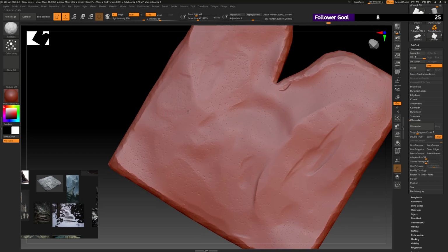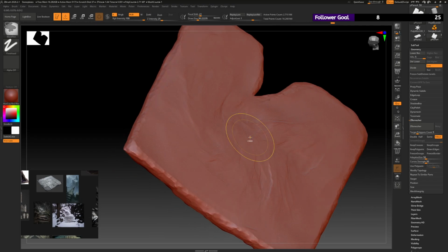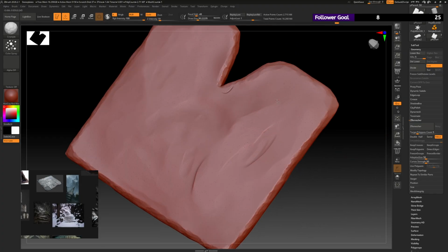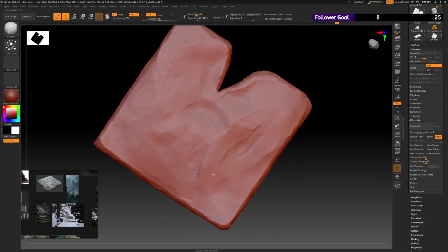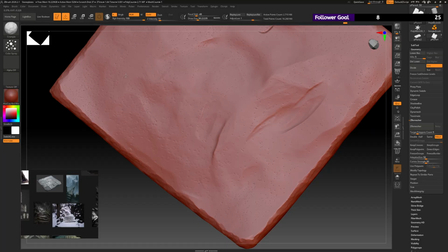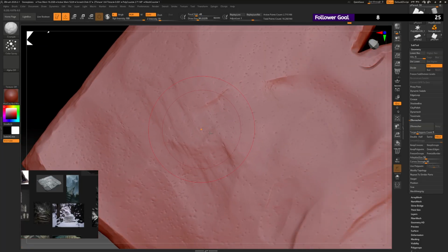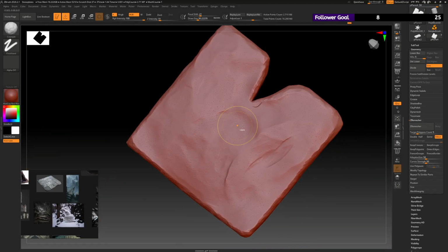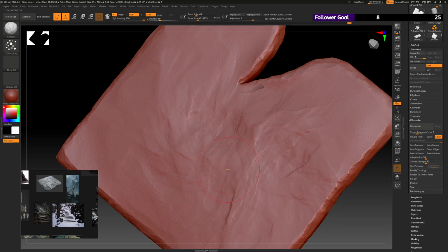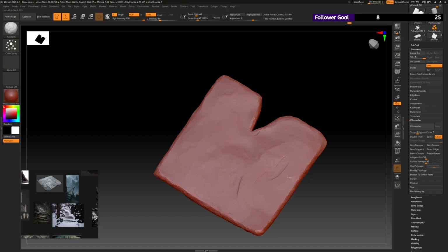The crumple tool is sort of like move topology. You move it around like this, and it adds crumples. It's really good for doing stone or anything that has a gloss texture. On stone, it adds those small cracks, which would usually take a while to add, but with just some movement, you can see it's adding those cracks. Although you need to be careful, because if you overdo it, it's going to start crumpling the surface and breaking it down, which could get quite annoying.